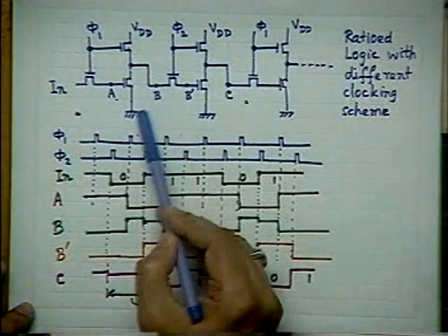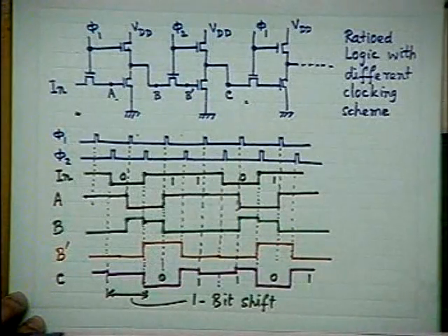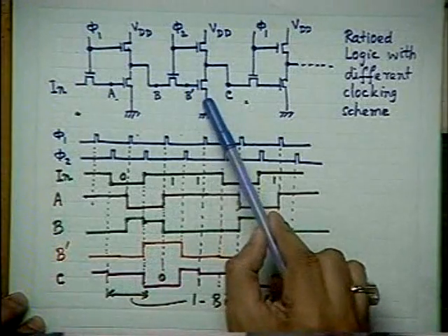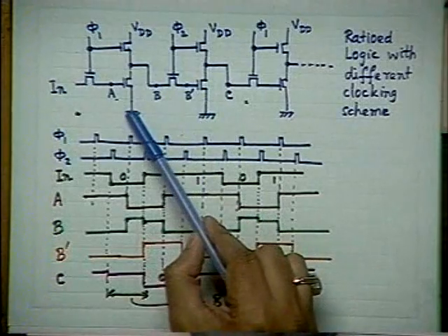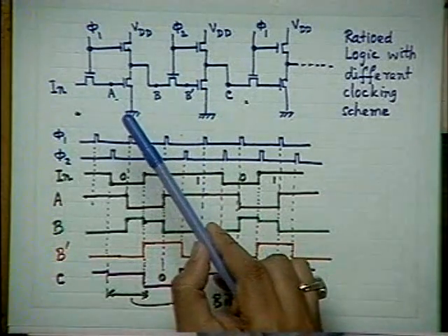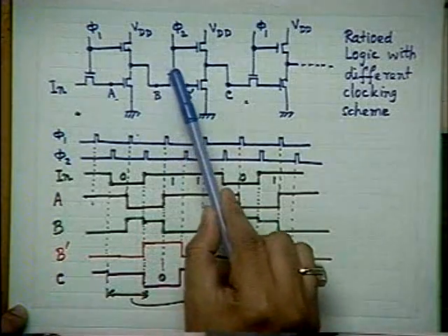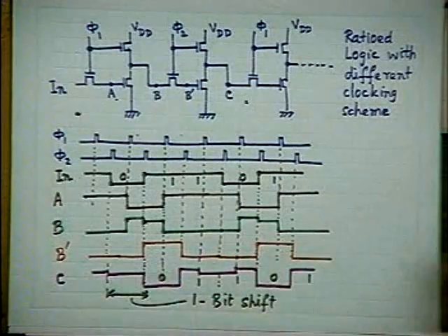Because if I have a large capacitance here, it holds a lot of charge when it is fully charged to VDD, and even if it loses a little charge, its voltage does not drop appreciably. If this capacitance is small, for the same voltage it will store less charge. If it is large, for the same voltage it will store a very large quantity of charge. So when phi 2 is on for a short time, this thing happens very quickly.